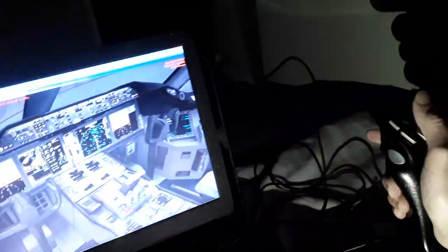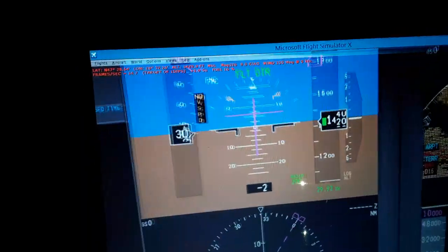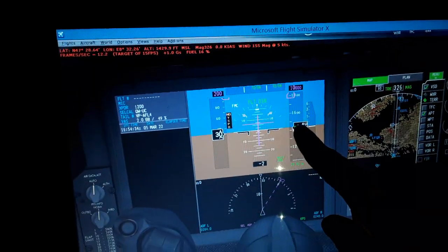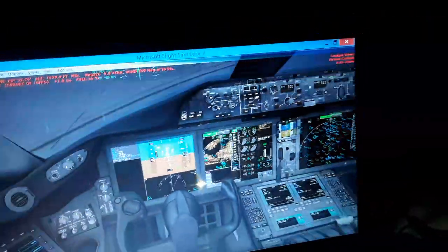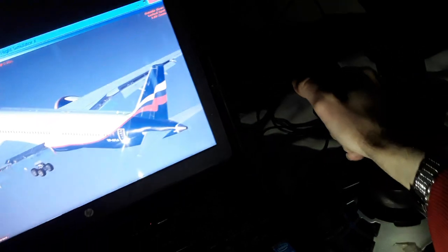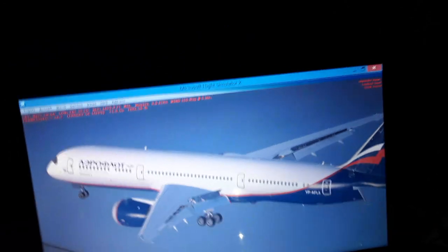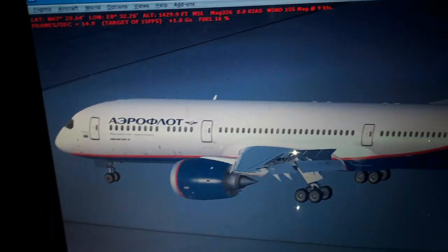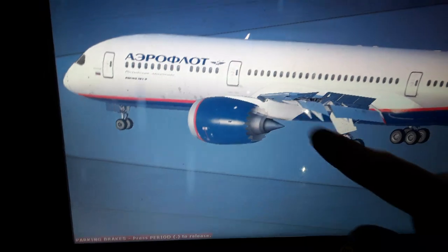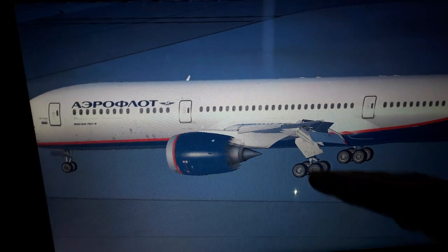Because the wings are going to lose the lift and make the aircraft start falling from the air, so we need to avoid that. You can see also monitor always the airspeed, the barometric altitude, other indications. I'm going to show you in a couple of minutes. So you can see also using the Bernoulli theory of fluids. So we have the vectors, as I told you, the flight control deflections, the airflow deflections as we fly. You can see the bottom surface of the wings is more flat. So also as the aircraft accelerates for takeoff, it takes an angle of attack like this, like 9 degrees for takeoff and for landing.